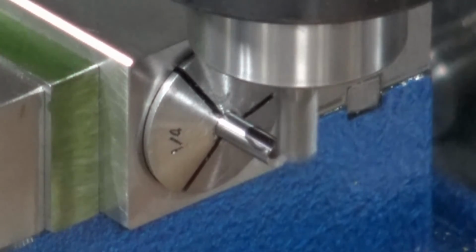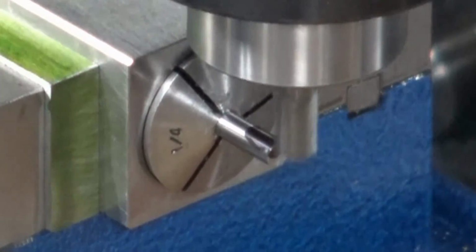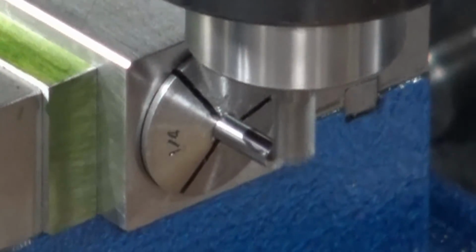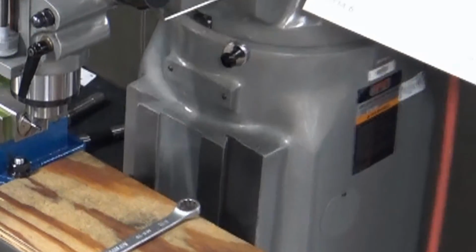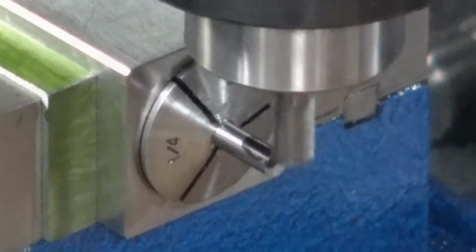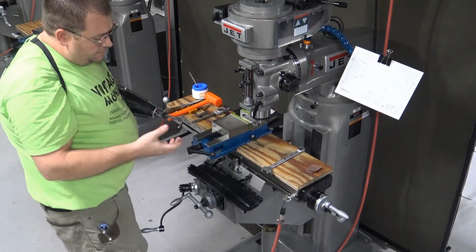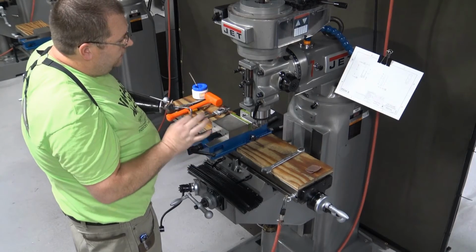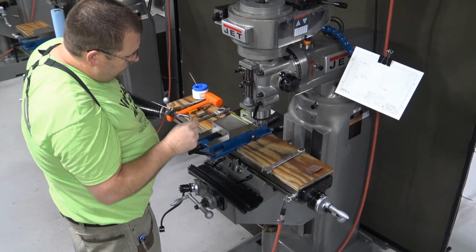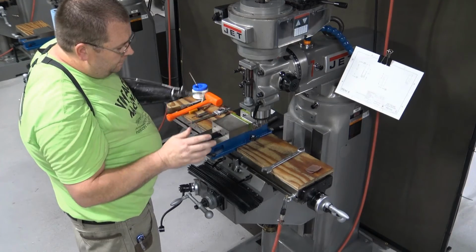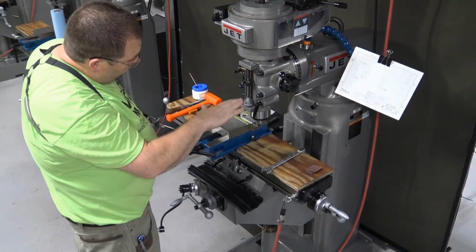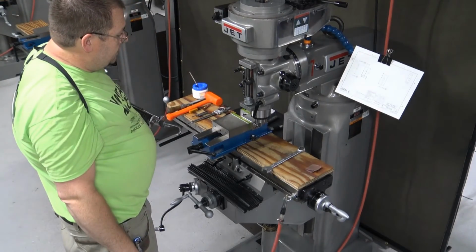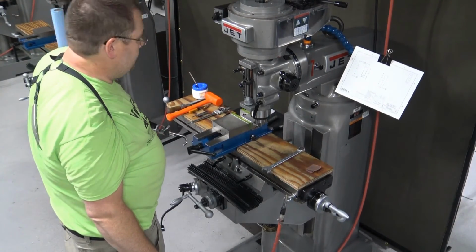I can hear it just ever so faintly. Tick, tick, tick, tick, tick. I'm going to set my dial to 0, and that'll be my reference for the length of my cut. Now if I drop the knee back down, the advantage with doing a real nice light touch off is I didn't actually machine a feature on there. All I did was touched off. My suspicion is with a piece of emery cloth, you won't even know it was there. If I don't go too deep, I'm going to machine that material away anyway. So that Y dimension is 620 thousandths.